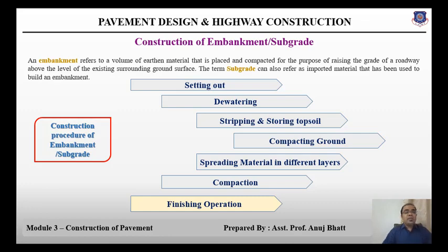The depth of the topsoil shall be sufficient. It should usually have a thickness of 75 mm to 150 mm. When the earthwork operations have been substantially completed, the road area shall be cleared of all debris, and ugly scars in the construction area responsible for the objectionable appearance eliminated.